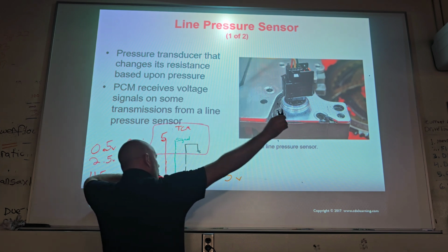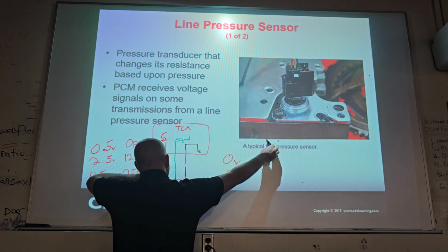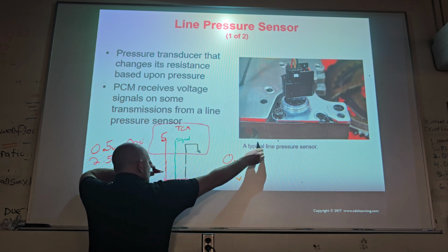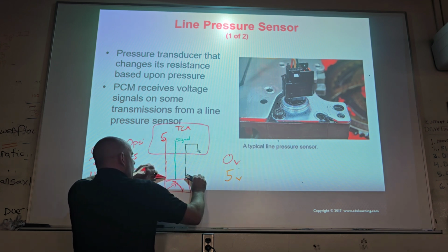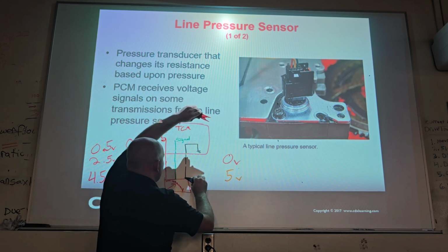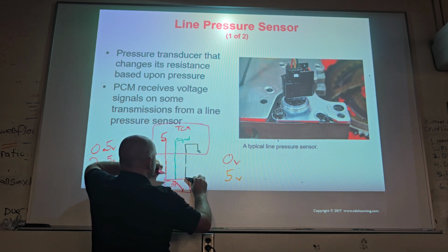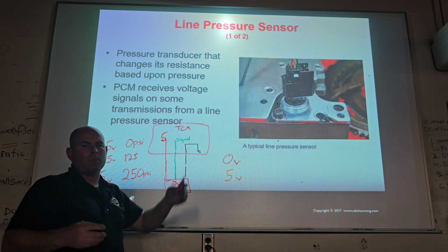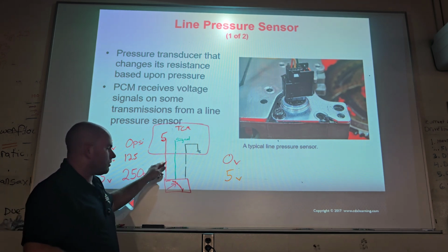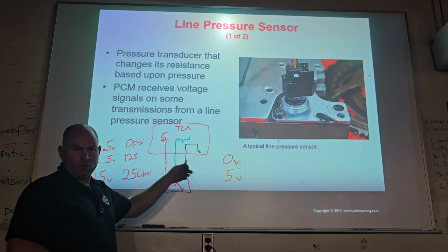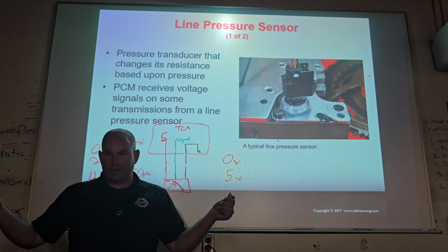Let me put this one on ground to the battery. Clink. Oh, it reads 5. That means 5 volts is good. Then you'd actually move this one over and you put this one on the positive of the battery. Clink. And that reads 0 volts. And you'd be like, oh, okay. No, it's right. You can determine, is it on the 5 volt reference side or is it on the ground side? Cool. Not that hard to diagnose, right?